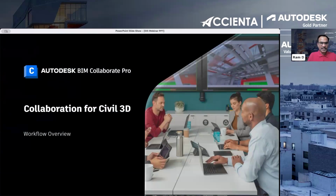prerequisites here. The version of Civil 3D, once you integrate with BIM Collaborate Pro, also matters. For example, if you're using the 2024 version of Civil 3D integrated with BIM Collaborate Pro, and you have another project where you have to use 2025, that also needs to be integrated again. So that's the way of integrating the cloud products as well.